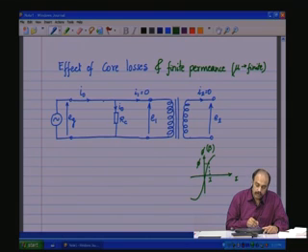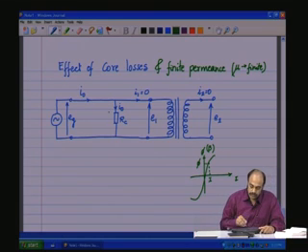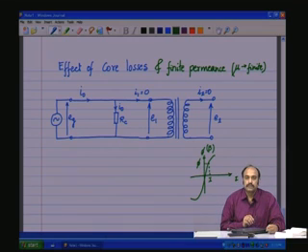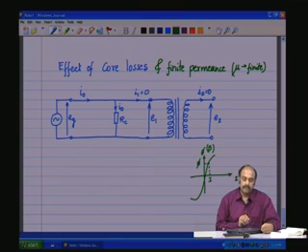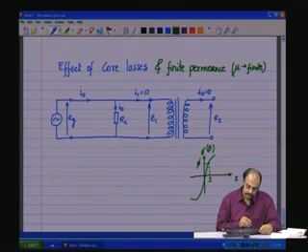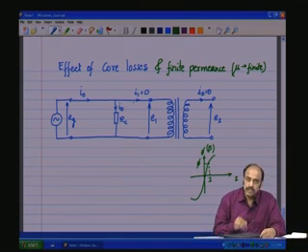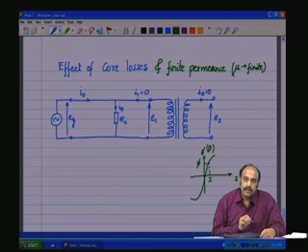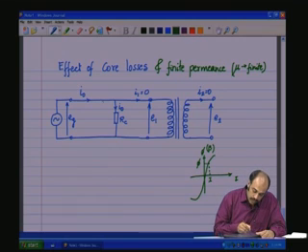That current is also to be drawn and diverted to the flux producing component of the equivalent circuit, and I1 should still continue to be 0 because this ideal transformer is not going to take any current to set up the flux. So, from here I am going to have one more component, and let us call that one XM.